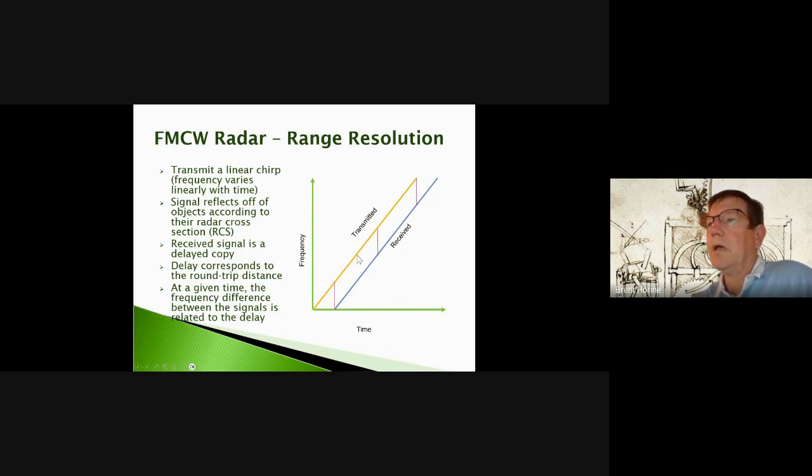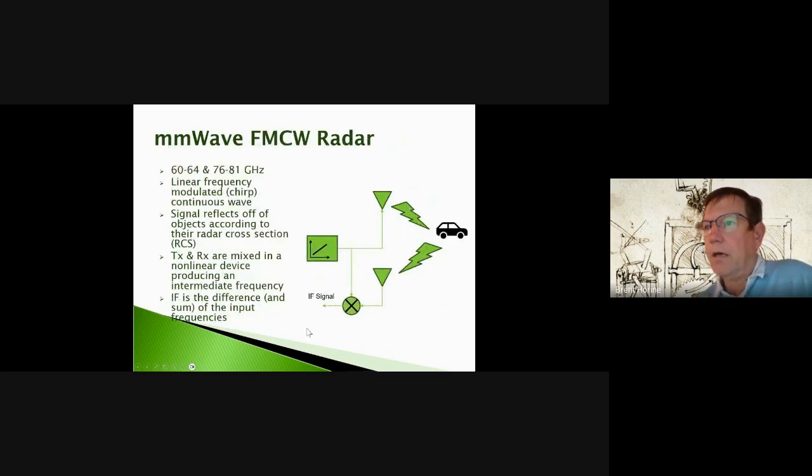So then this waveform gets transmitted and it reflects, and sometime later it comes back, and now is presented back to this mixer, right? So as we're transmitting, we sample that transmitted signal off, couple that to the mixer, and then we also couple the receive signal.